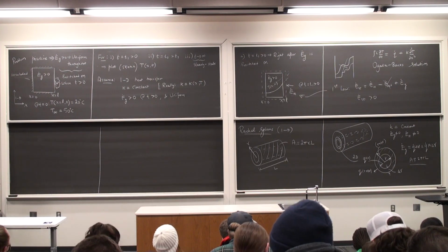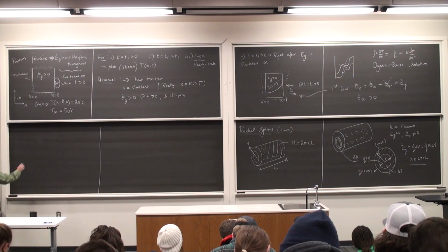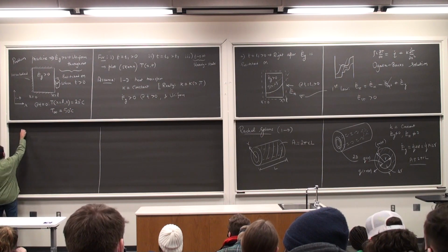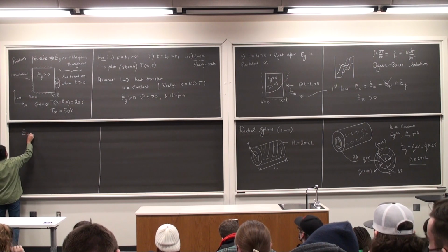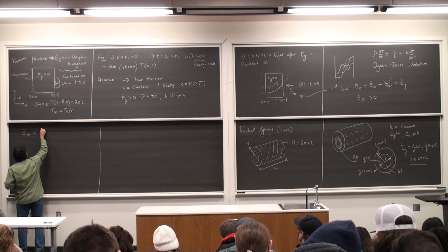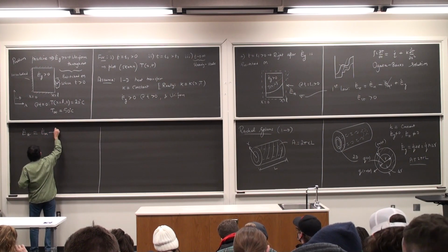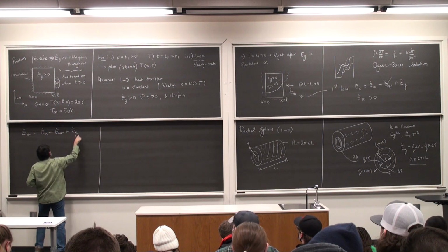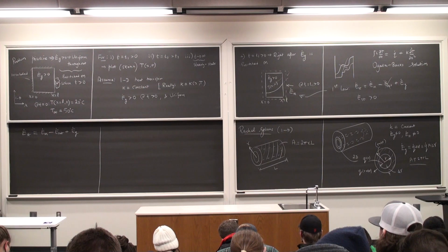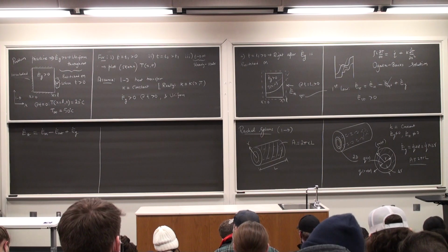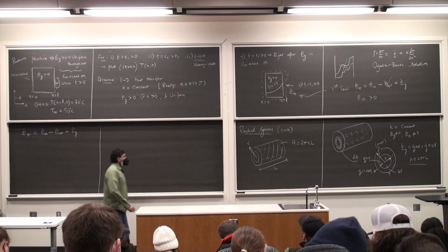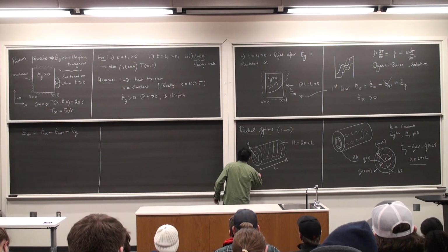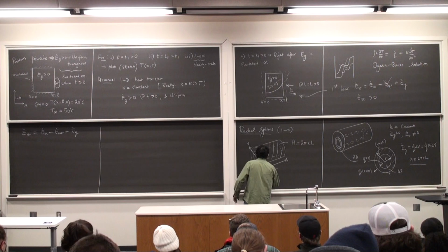And we do something similar to what we did for the one-dimensional heat diffusion equation for plane walls. I start off by writing the energy balance using the first one. E dot stored, E dot in, E dot out, plus or minus E dot generated. For the time being, just assume that Q dot is greater than 0, so maybe let me write that down. So say Q dot is greater than 0.